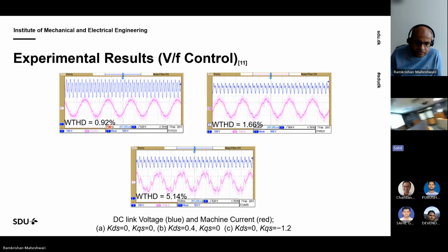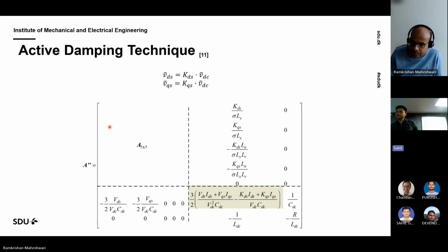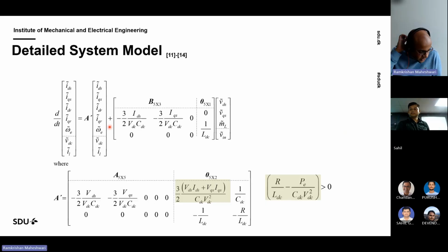Sir, I have one more question. Since you have a grid connected system with a diode-based rectifier, with the reduction of the DC link capacitance, are the effects of non-ideal grid being considered there? Like if the grid is non-ideal or a weak grid, what effects do they have on the small DC link capacitor? We haven't considered those things, or haven't analyzed.